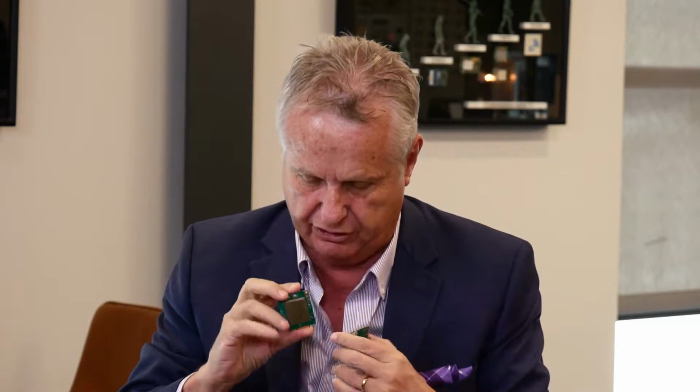But you show these little radios, and you've obviously got a lot of experience of working with different types of radios. How easy is it to swap out? Let's say DSRC changes to DSRC 2.0. How hard is it to actually swap out one of those? Well, as it happens, there are 2 little screws over here which secure it, and there's a plug at the bottom. It's called a PCI Express socket. And so this just clips in. And so it's an inexpensive, easy thing to do to change out the radios.